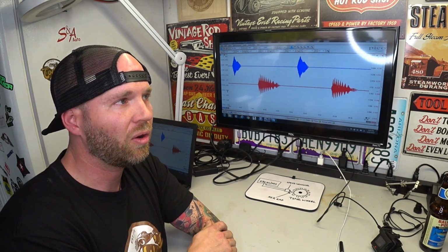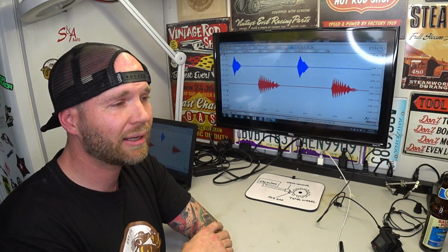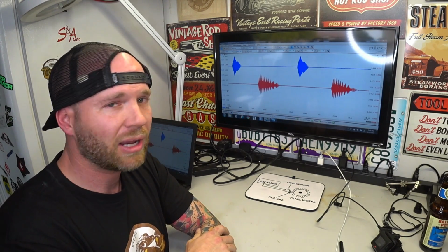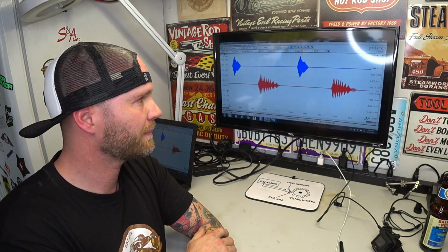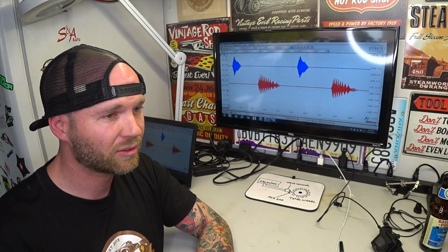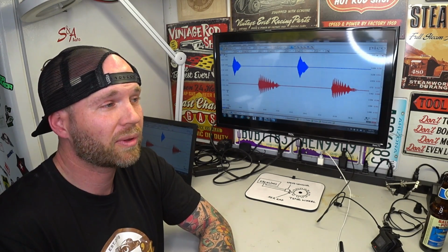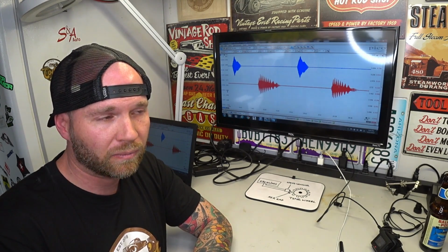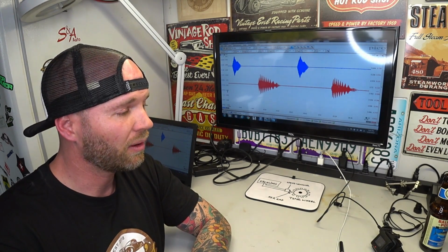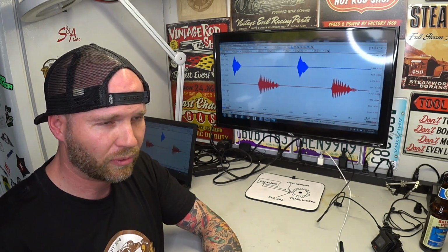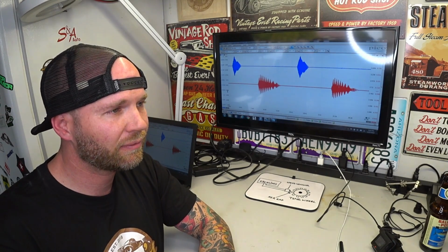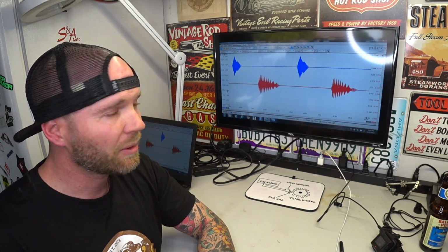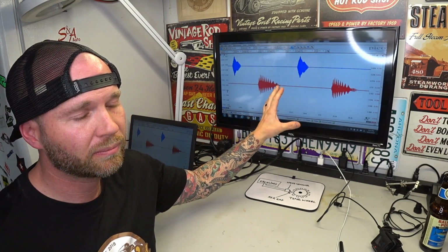Trust me, I did it for a long time. But just doing that, unfortunately, there's times that you're not going to see everything, and that's where having a scope is a must. I mean, anymore with these electronics and stuff, you can't just diagnose a vehicle on scan data alone. Scanners have gotten better. Don't get me wrong; they have gotten fast. The bidirectional controls, the displays, I mean, they've come a long ways. But there's always going to be a need for a scope, okay?